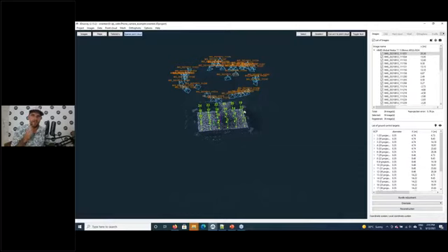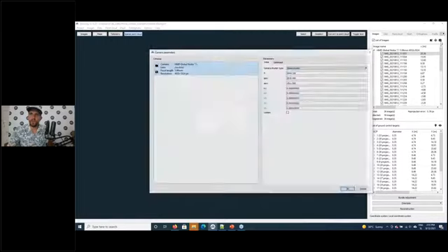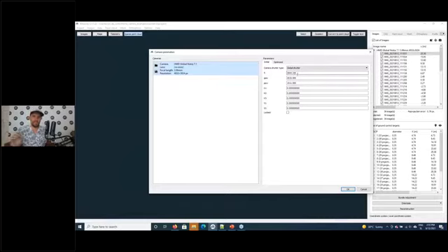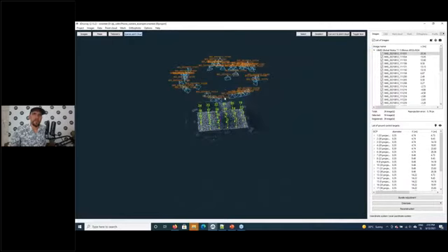If we use the same phone to maybe map a building or something big, you would probably expect this value after bundle adjustment to change by some 10, 20, 30 pixels, something like that. Not much, definitely less than 5%, but this focal distance is for when we are mapping something close. When we have bigger things, we can expect it to be slightly different.